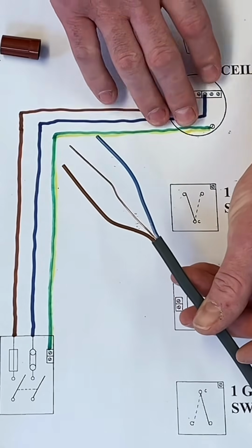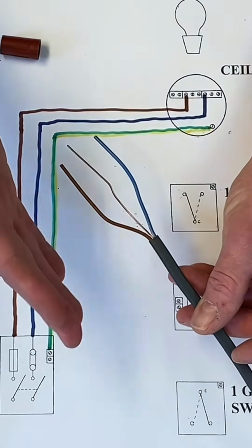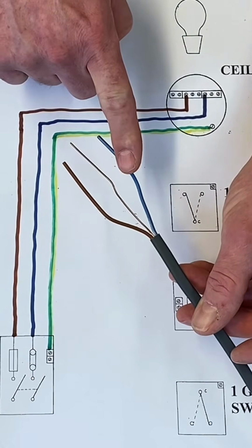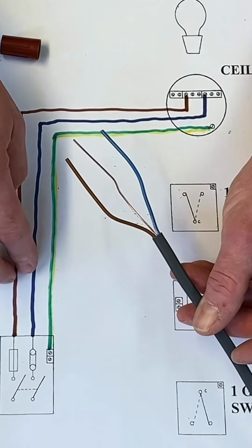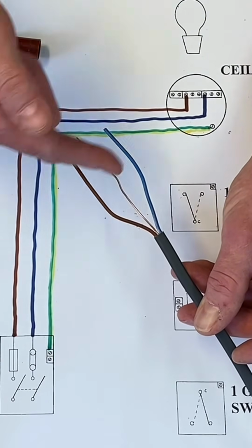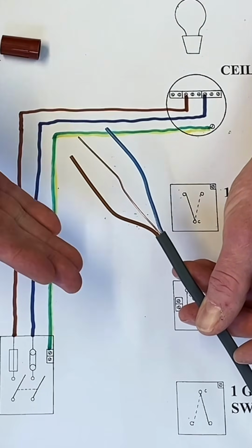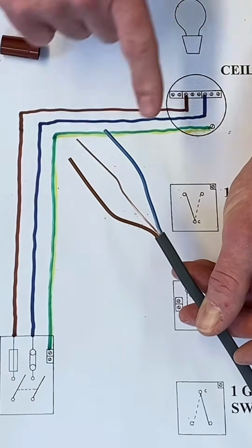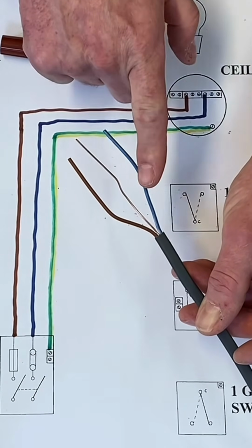I've kept these drawings using twin and CPC because you see it a lot in industry, the twin and CPC going down to a switch and identifying the blue conductor differently. And we'll talk about that again. And also other colleges tend to use it as well. So I'm just trying to push our learners. Our learners will probably use twin brown. They'll be able to adapt. The rest of the world is probably using twin and CPC and identifying this one.